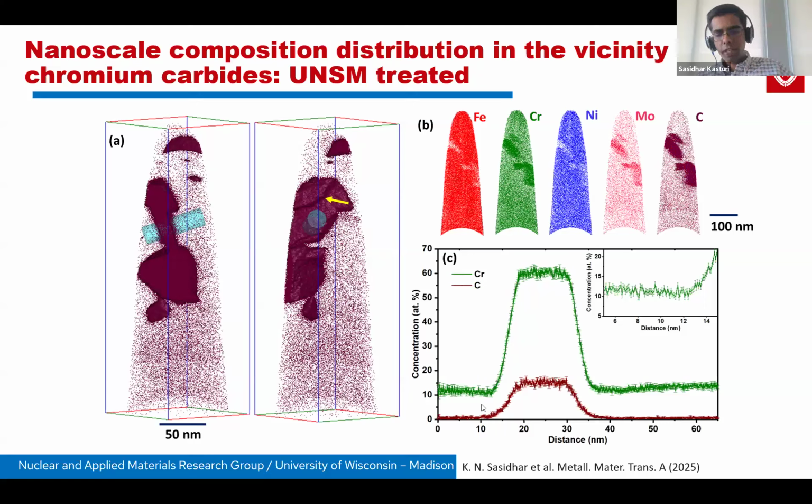And that's a very different region of the material that will have very different grain structure and mechanical properties, and the composition will depend on the filler material that you use, but the heat affected zone typically is not affected compositionally by the welding process. Bulk composition is not affected. The microstructure locally is varying here, but the overall composition is the same because there is no liquid phase mixing, and that could extend several millimeters, I think. Quite big, yeah.